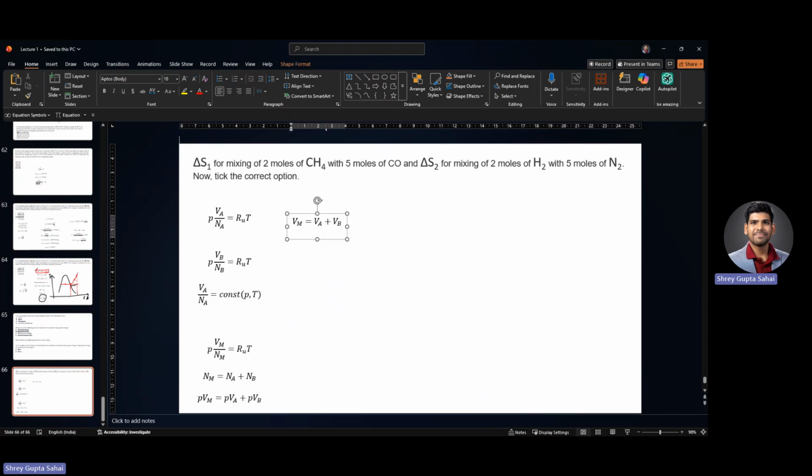Okay, and now this is the part. Individually, a gas was occupying a smaller amount of volume, and when you mix it, it is kind of expanding without giving you any work. You know that when a gas expands, like in a turbine, it gives you some work, it gives you some exergy. That is lost when you mix it. And that is why delta S has to increase.